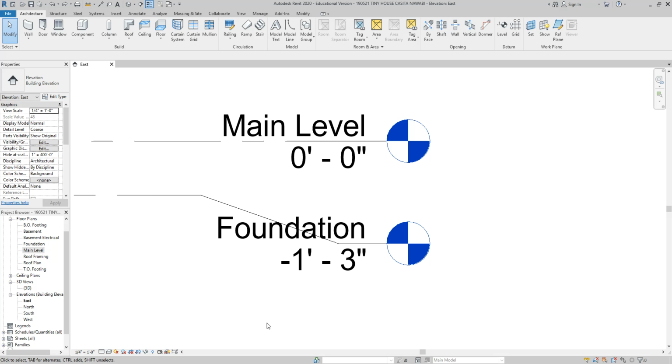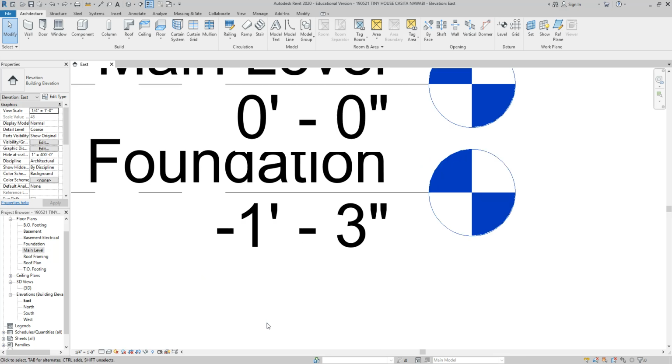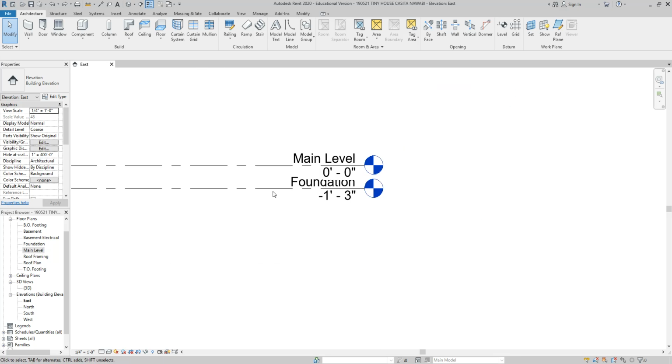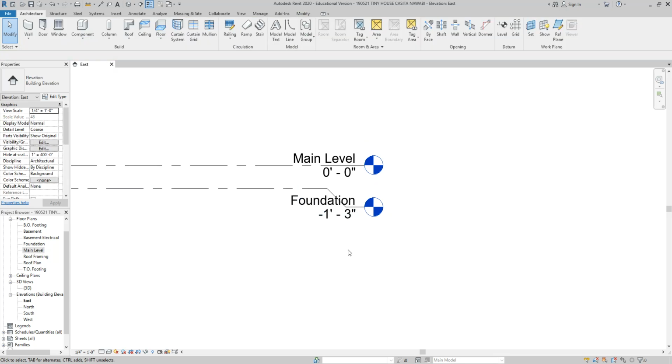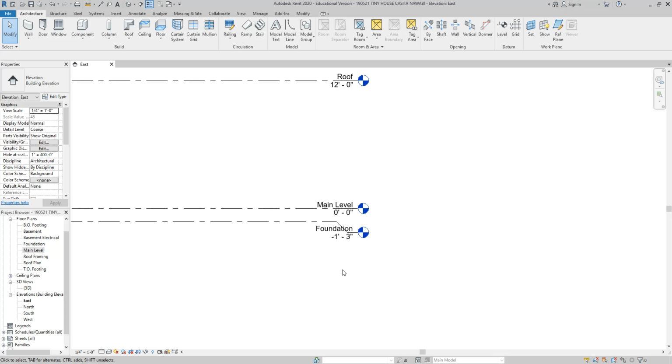Okay, I'm going to do a Control Z. I'm going to show you that one more time. So this time I'm not going to zoom in, but if you click on it, even here, you really have to be looking for it. Once you hover over it, it says Add Elbow. You click on it and it automatically drops it down. Okay? Every once in a while, once we start adding more and more levels, you might have to add the elbows. Okay? Everybody got that all right?